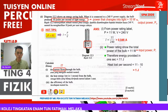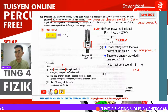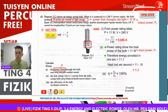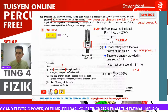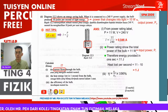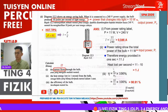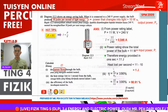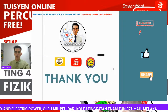Okay, then the last question, number 3, you need to find the efficiency of the bulb. This is a formula we learned already at Learning Center 5. The question gave us the output power, which is 10, and the input power is actually 11, which you get from the power rating. You just substitute in this formula, so you get your answer 90.91%. So this will be the sample question of section B, which is related to subtopic 3.4 today. That's all for my sharing today.